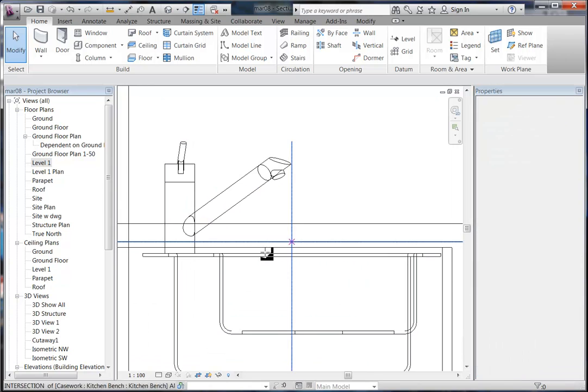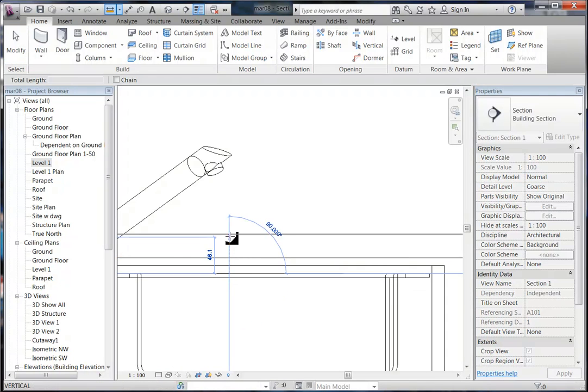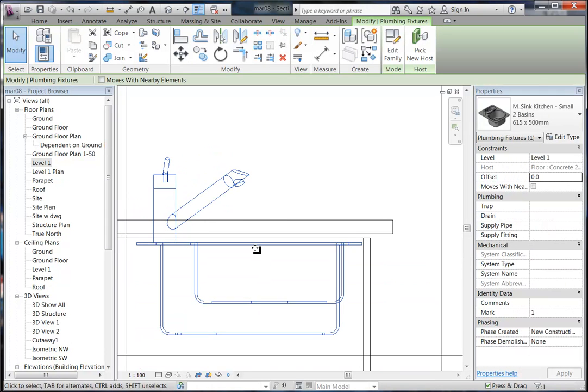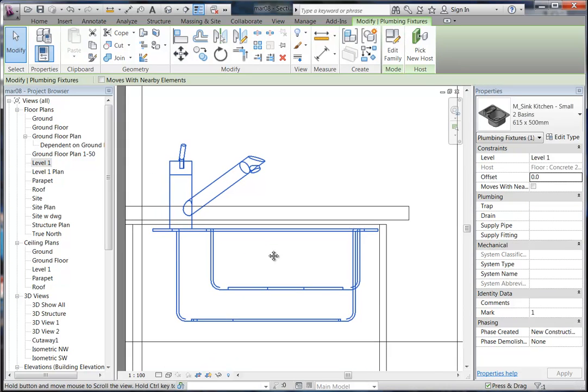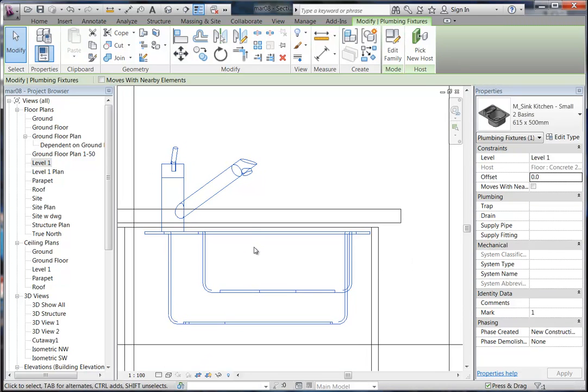exactly how far it needs to be moved up. So it's only 50mm down. 850 is used as a bench type by people who haven't done many kitchens. I would never do that again. Having worked in one, it's just too low for people who are an average height, and it really does damage your back. 950 is actually becoming more common than 850, but I know a lot of smaller stature people prefer the 850 benches, but I think 900, you know, there's a reason it's standard.